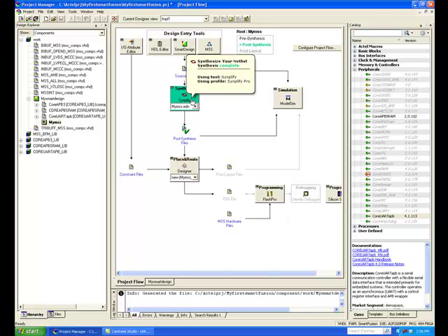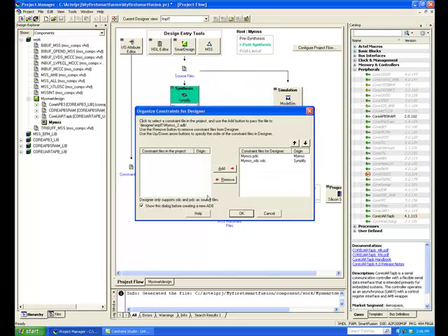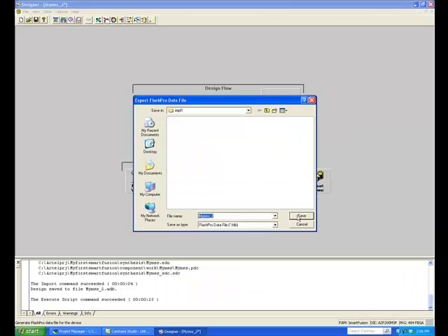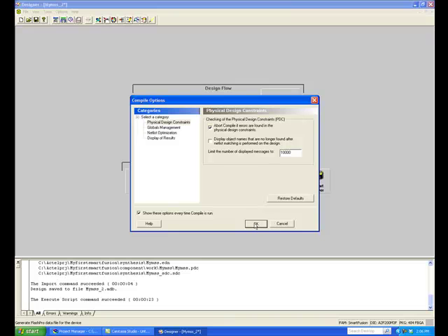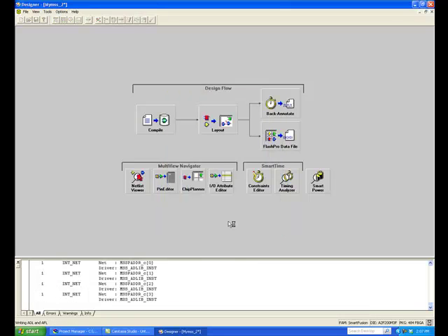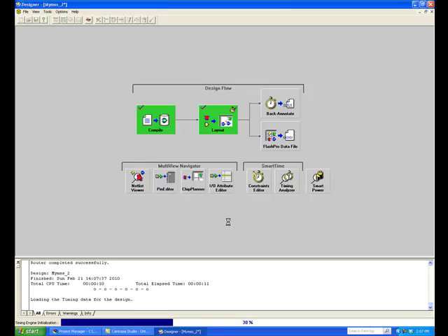After synthesis, click the Place and Route button on the Libero Design Flow Guide, and Designer will import the netlist. When Designer opens, click the FlashPro Data File button to accelerate through the compile and layout and generation of the programming file. Accept or change the various dialogues that are presented as compile, layout, and programming file generation are automatically completed.